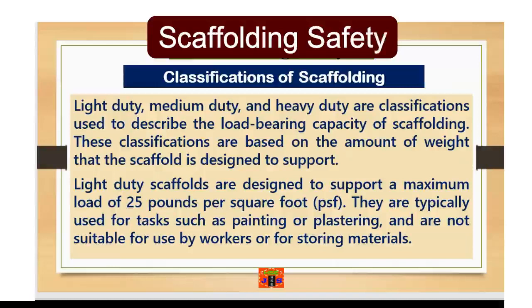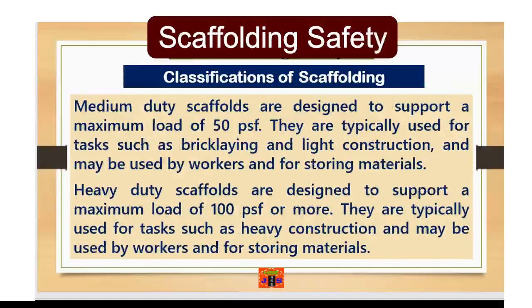They are typically used for tasks such as painting or plastering and are not suitable for use by workers or for storing materials. Let us understand now medium duty scaffold. Medium duty scaffolds are designed to support a maximum load of 50 pounds per square foot. They are typically used for tasks such as bricklaying and light construction and may be used by workers and for storing materials.